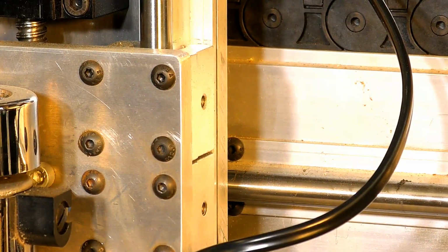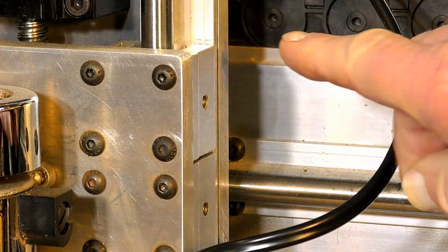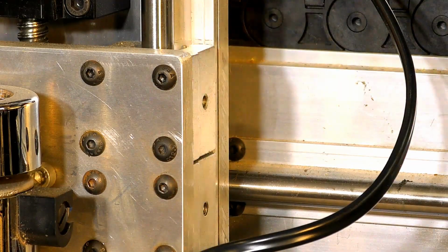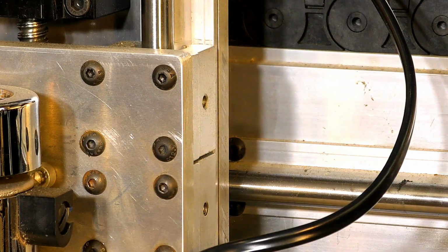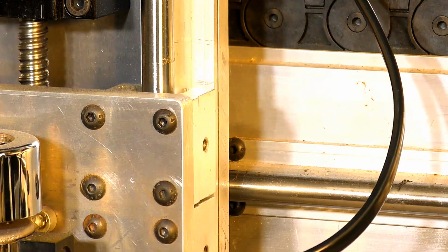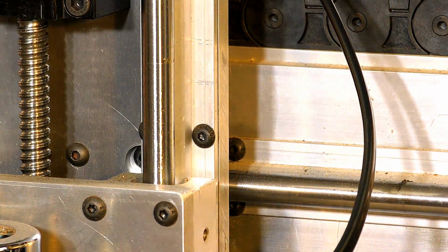Okay, now I've done it about half a dozen times, and I've actually remarked the line up here, so it's about a millimeter further up. So now we're going to do 5 pulses, which is exactly 50 millimeters. And I think you're going to see that that's pretty well good.